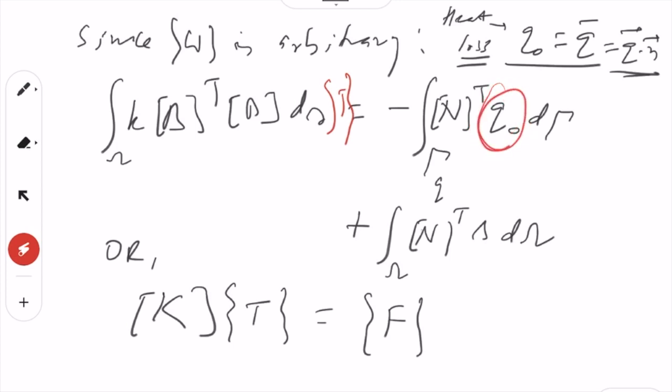So a contribution also comes from the boundary. So heat loss, hence minus here, the heat gain, hence plus, this is for the whole domain, this is body force, this is kind of traction, right. So this force has these two, where this one is K, the whole thing is K, this is T, like this one. So this we have discretized basically, and we have got this one. Now what remains is the details, like what is the value of B, which you obtain depending on N and all, right. So that is what it is.